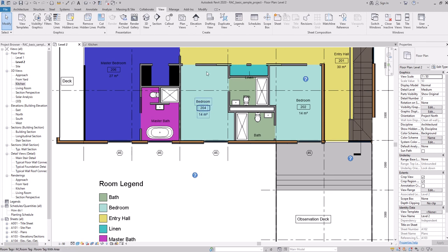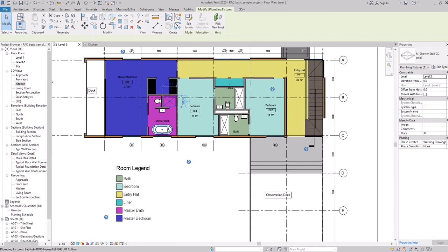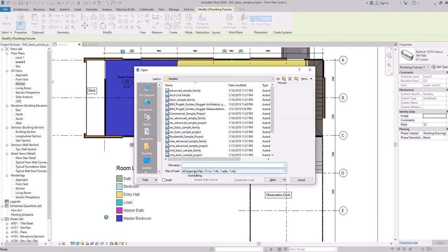One more thing that we've mentioned in the last video, that in Autodesk Revit we have families and we have a project. So when I go to File and Open, okay, you will see here that we have all these supported files. So basically, when you have any Revit file, if it's a family or if it's a project, it will show the same thing. They will all have this blue rectangle here, blue icon.